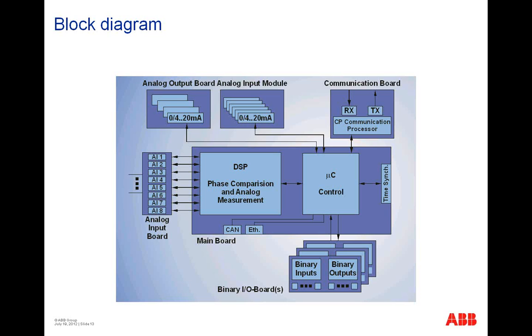In this moment we take all the measurements all the time from the voltages, from the main incomer, from the standby feeder, from the busbar. Such a device calculates synchronism, phase angles, frequency differences, voltage levels, and so on. And this will collect all the data all the time.